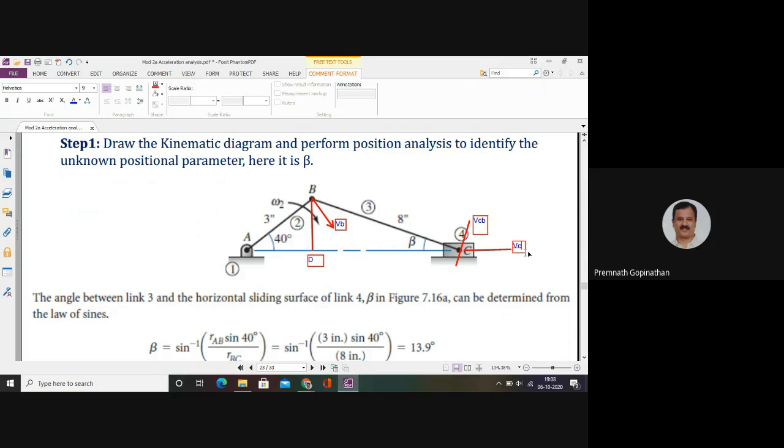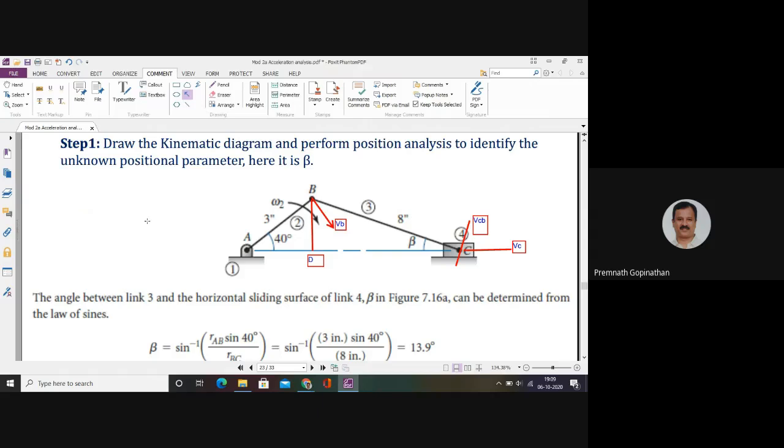So now you can identify the velocity polygon. I'll draw it on the left side. First I'll draw the vector representing VB. That has to be parallel to the vector shown at point B. So this is VB, right? And correspondingly, I can draw VC, because I already have the line of action for that one. Right? This is the line of action of VC.